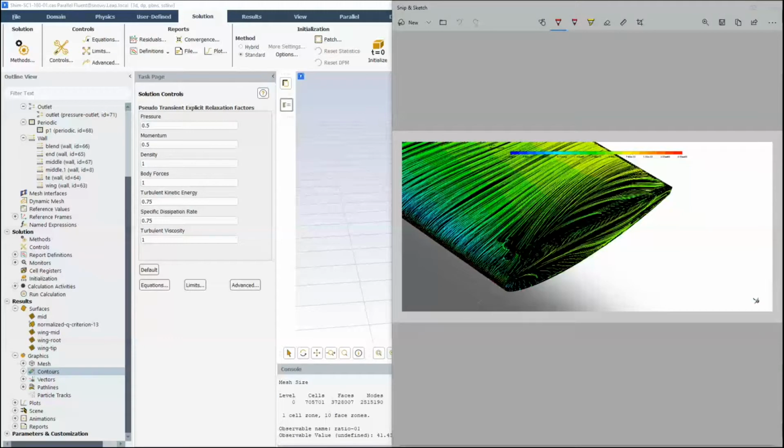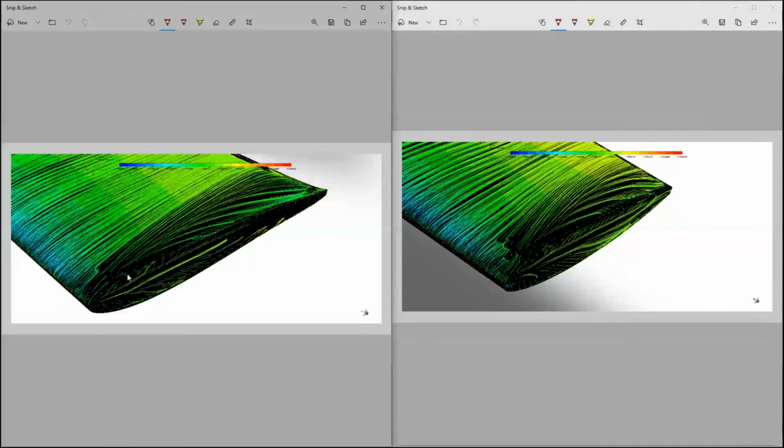Now it's hard to see the shape change exactly, but you can see that we've twisted out this trailing edge to keep the flow attached for longer, and that's going to allow more of that force to be realized. So it's actually increased the size of this end point, and you can see that the flow is in less separation. There are little separation bubbles here.